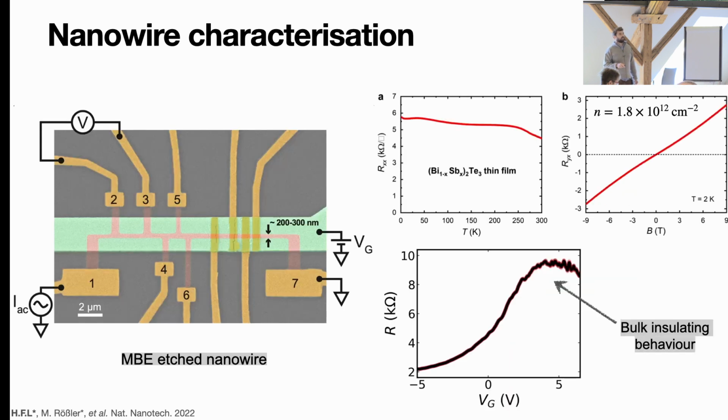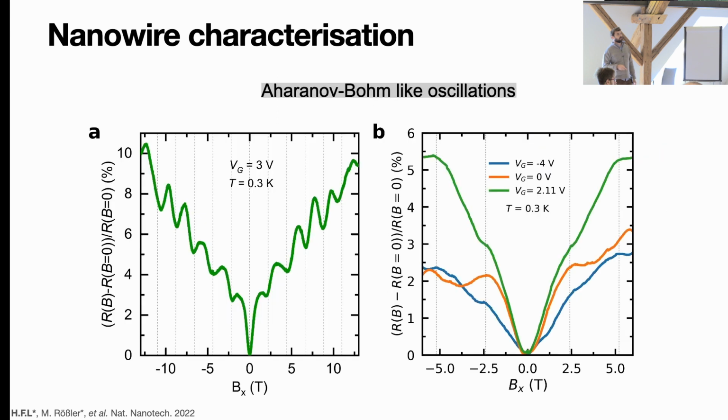As a function of gate voltage, you see that there's an increase in the resistance, and you see these little peaks and dips, which are not as clear as in the previous data that I showed. But the expectation is that these are coming from these quantum confinement features, so the fact that I have the subbands and therefore Van Hove singularities is increasing the resistance.